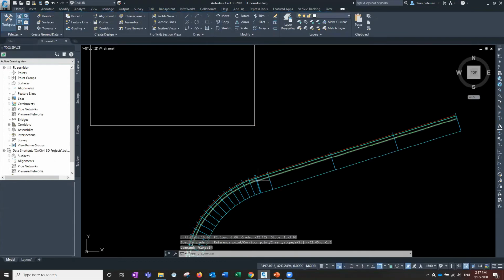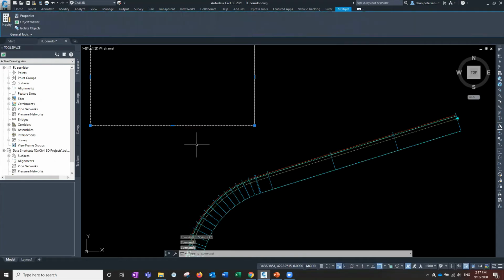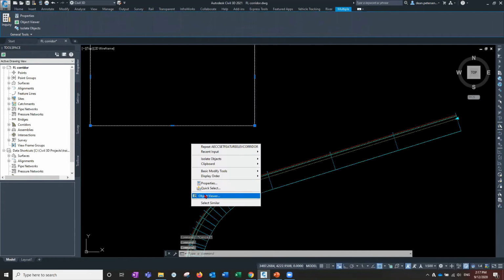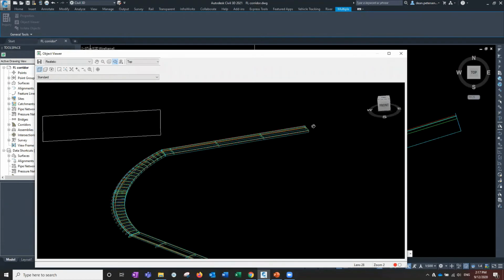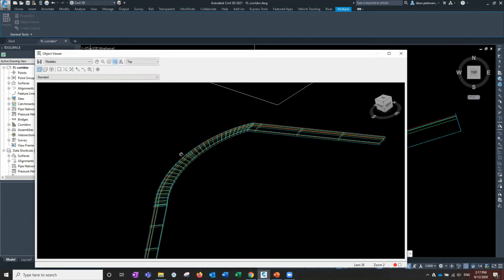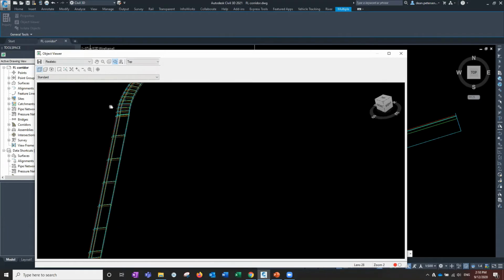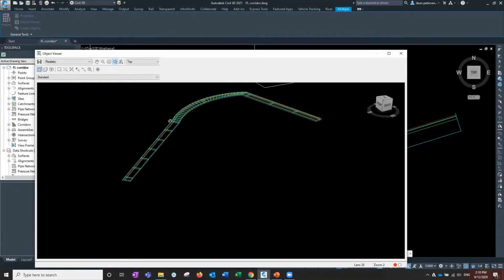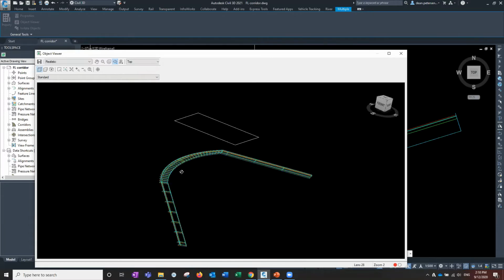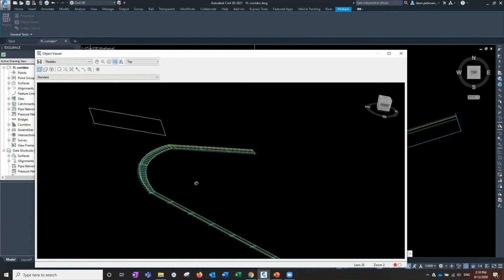All right, so having a look at this thing, picking the corridor again and the platform, the object viewer, we've now got the heights of that set by those reference grades from that object. The rest of the corridor and feature line is just going back down to its original elevation and position, basically to the next vertex. The thing about this though, it is non-dynamic, it's a one-off.